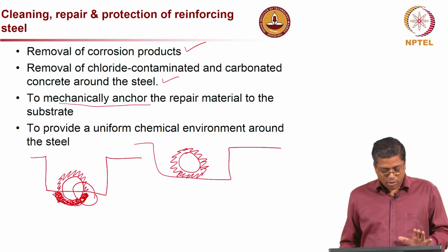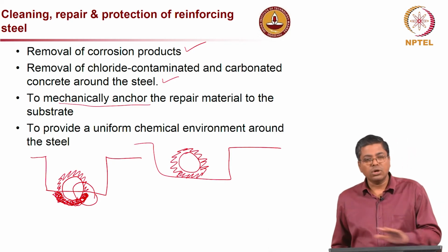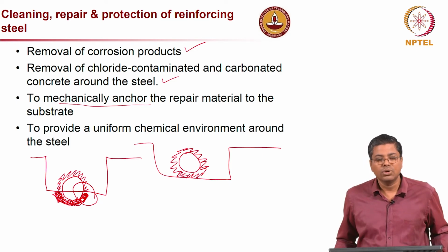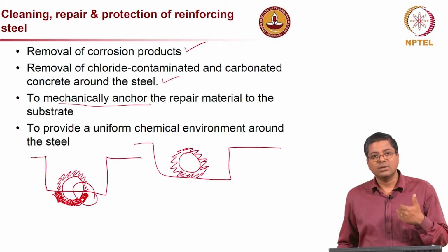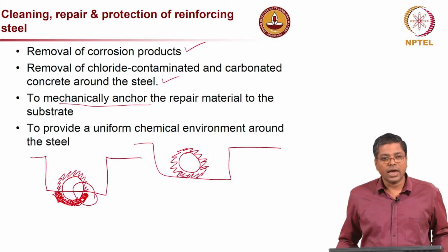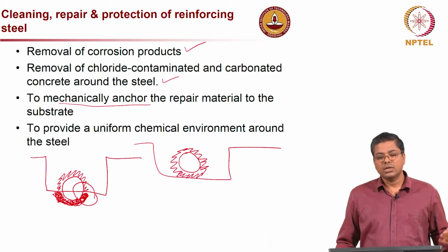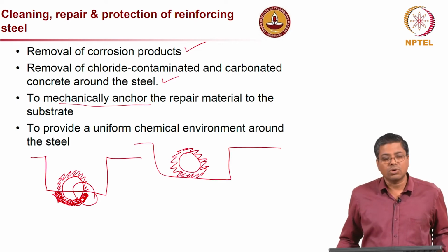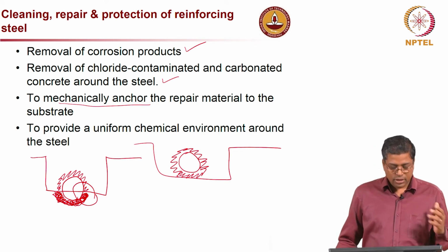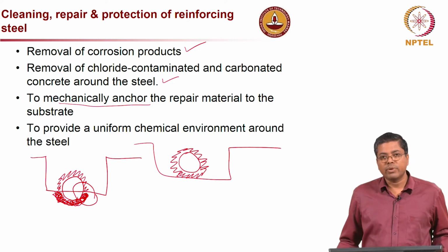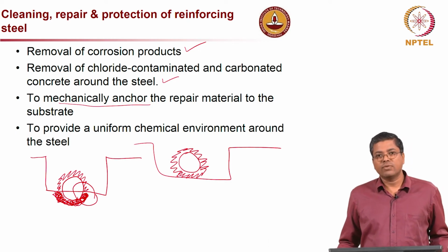This is the problem, because most of the time we do not do all this cleaning and do not do the repair work properly, and then what happens is in another 3-4 years the same steel continues to corrode, and then there is a significant problem, and then the repair fails. So, this is where cathodic protection and this proper preparation of the concrete surface and the steel surface becomes very, very important.